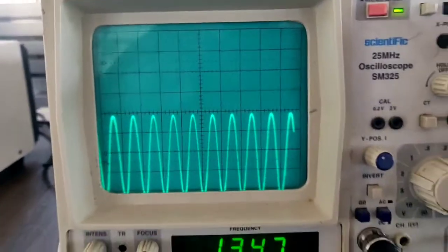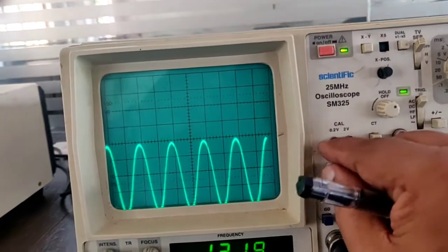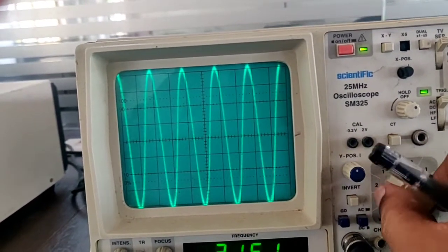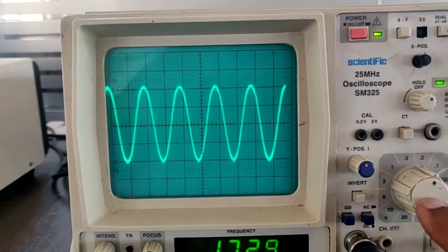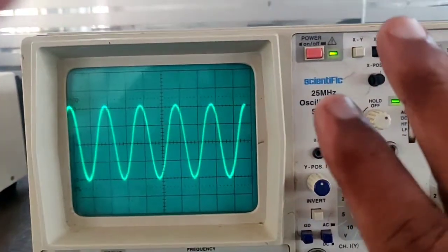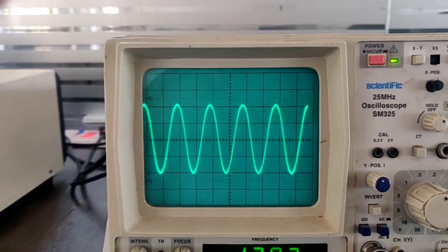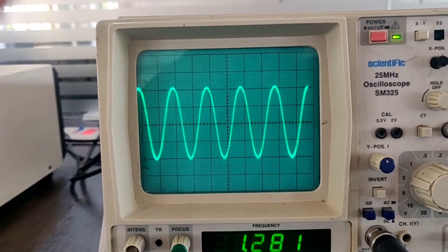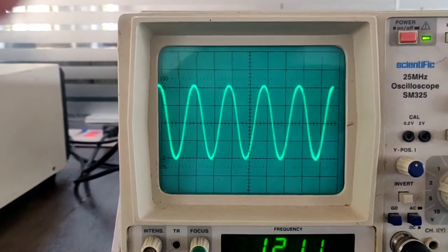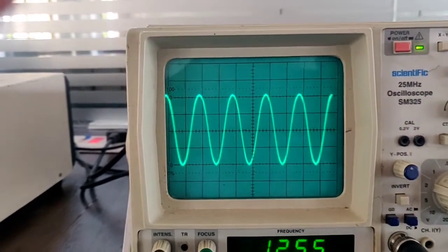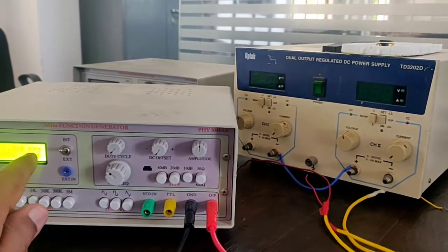If you want to expand this towards the y-axis, adjust this. That means the time base control, or adjust these to position it. You can make it big or small. Many students mistakenly understand that these controls will set the voltage. Sorry, the CRO will show whatever input you feed, the same value it will show. It is just like a mirror. Whatever costume you appear in front of the mirror in, it will show the same as it is. Don't assume that the CRO will do all this magic. It will just measure. It is a measuring instrument. But the input can be adjusted from the function generator.